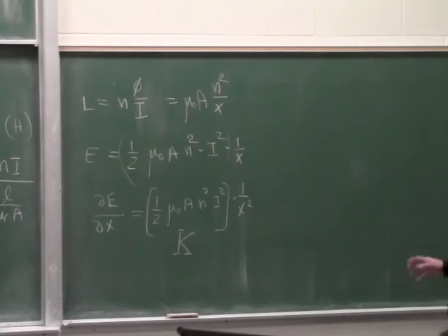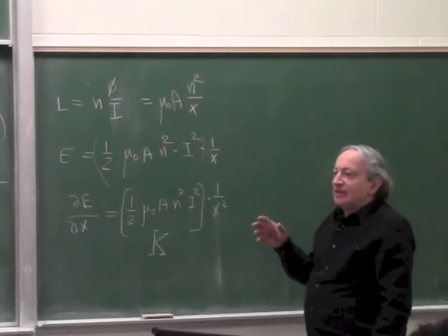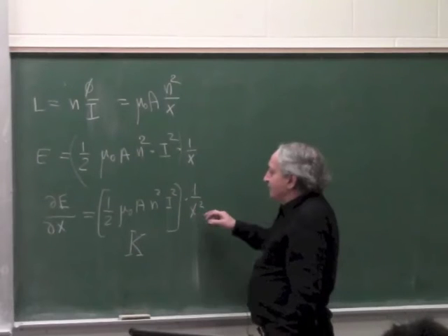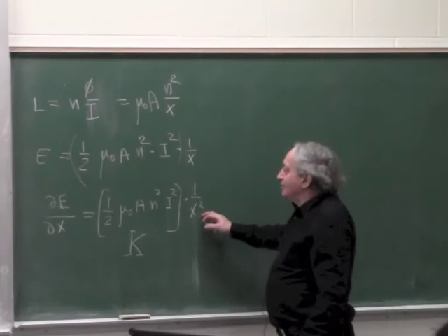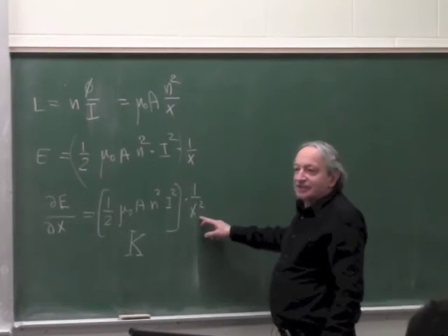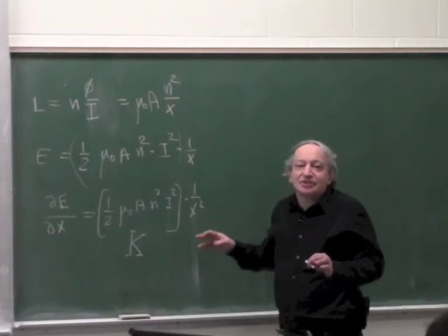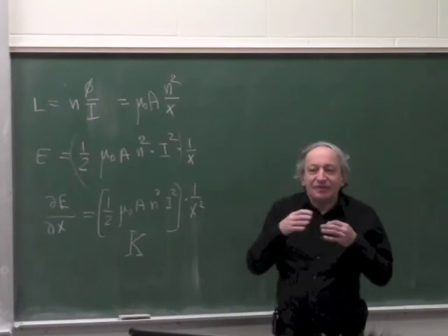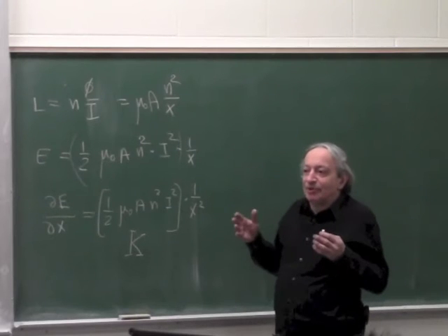So basically, if we take an electromagnet, the force is not going to be linear with current or distance. It's going to be square with the current, nonlinear with current, and inverse square with the distance. But all this just means it's nonlinear. All this doesn't explain snap. Because the fact that it's nonlinear is not such a big problem.